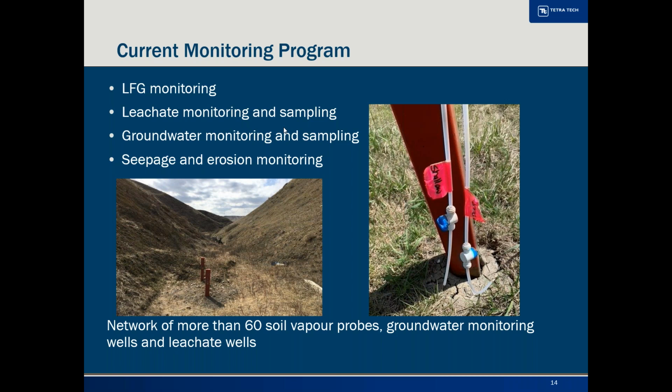The challenge for this site is the steep topography and the difficulty sometimes to access the places where you would want to install monitoring wells because of the slopes and depth in which you have to drill. If you drill on the top of a coulee, you basically have to drill dozens of meters more than if you were actually at the base.